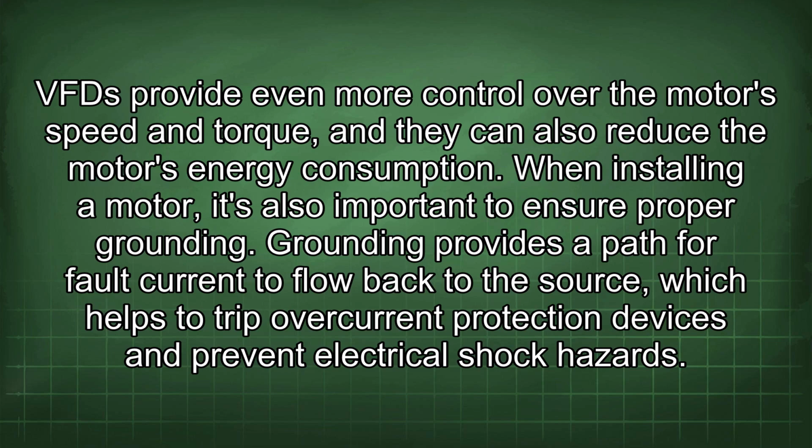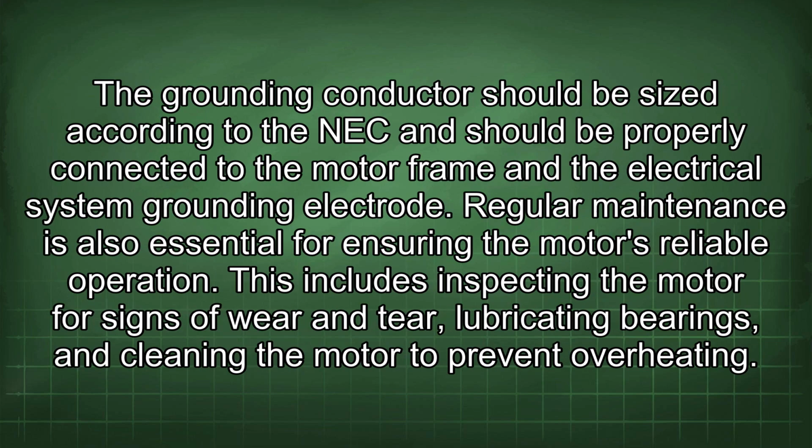When installing a motor, it's also important to ensure proper grounding. Grounding provides a path for fault current to flow back to the source, which helps to trip overcurrent protection devices and prevent electrical shock hazards. The grounding conductor should be sized according to the NEC and should be properly connected to the motor frame and the electrical system grounding electrode.